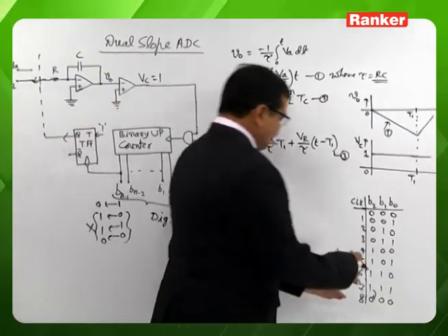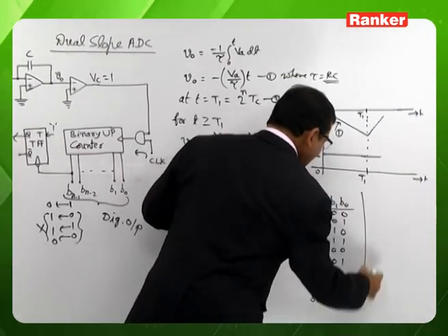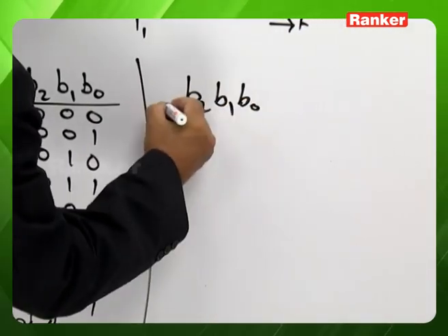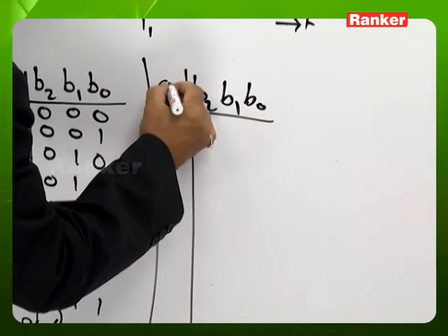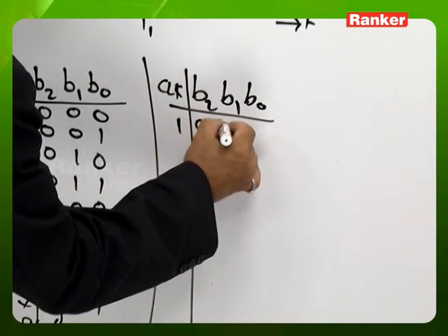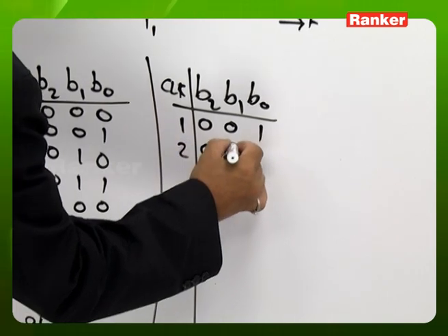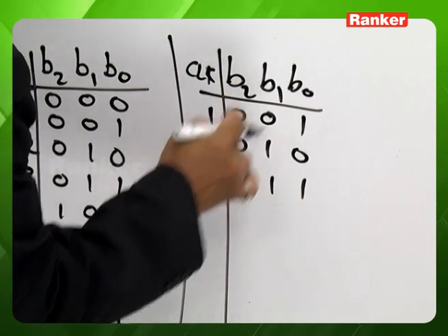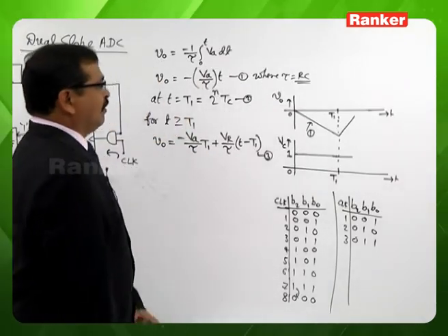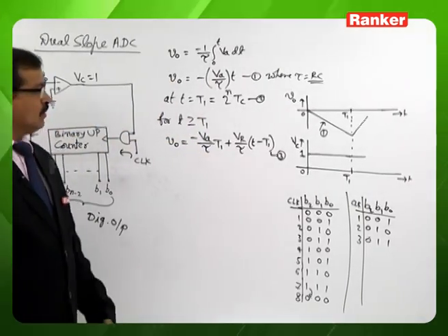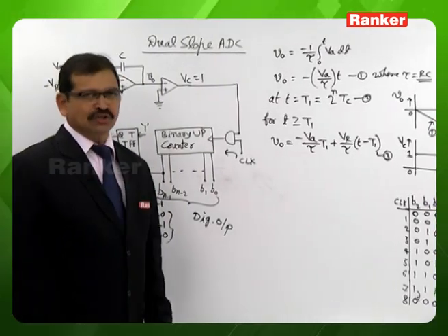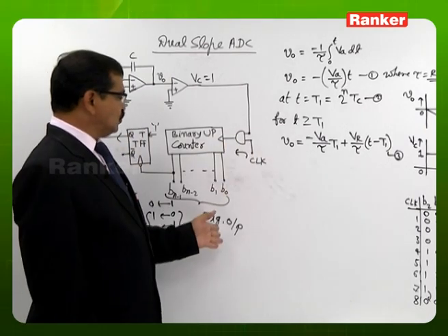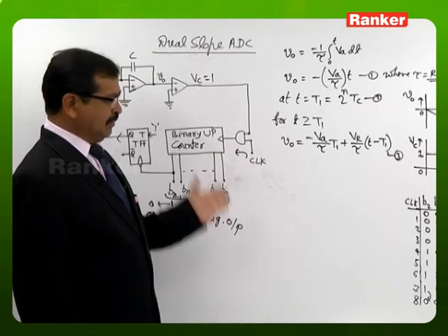It means after completing this full length, now the counter output is going to start again with increment. As and when the clock is coming, it is going on getting increment, and so on. So this positive slope line, as long as it is below this time axis, below this reference voltage 0, the clock pulses are allowed to pass, so that counter values go on getting increment.